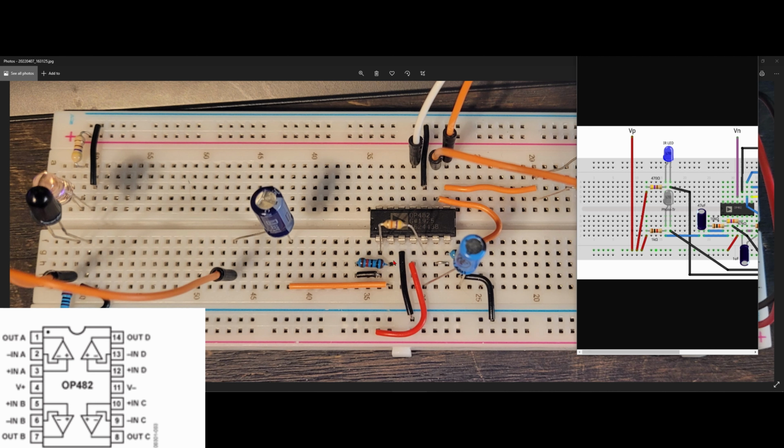Here we have this small, short little wire that goes out from the first pin, well, technically, because of the way that the op amp is, we have our input and output for this, 2 and 3. So 2 is this resistor, and it's ground right here as well. So ground is going to go into this third pin. We have this resistor going to the second pin that's coming from the input, or the output, sorry. The first pin's the output. So we have output going this way into this resistor, going back into the op amp. So that's how that first op amp is wired.